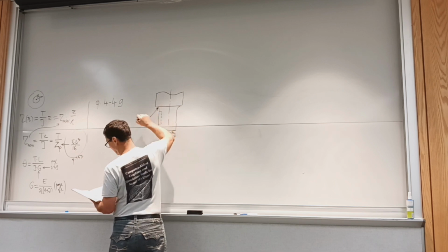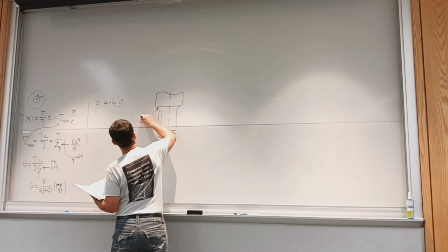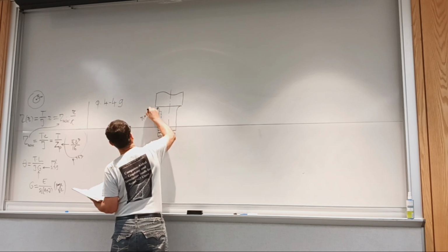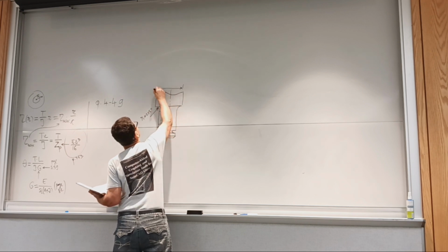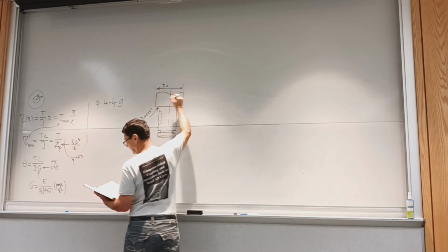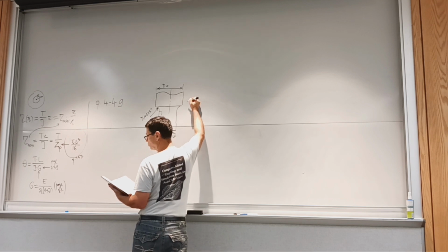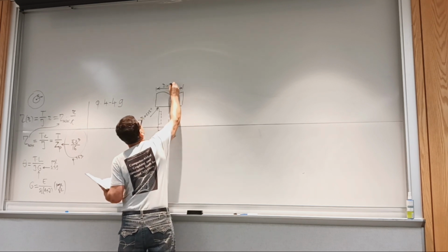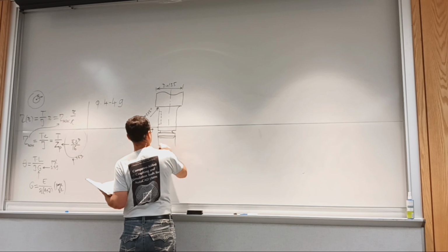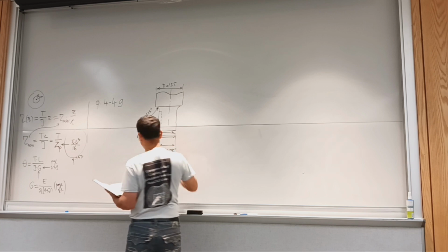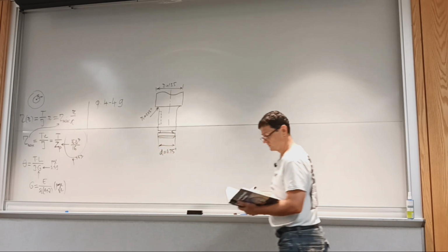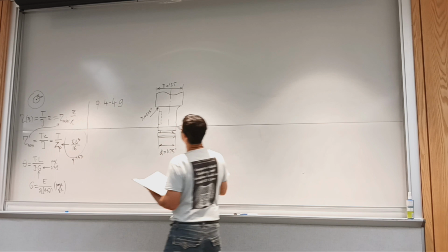Okay, we have R is the fillet radius of 0.05 inches. We have the major diameter D, and this is 1.25. And I made this 0.75, although it might be a too severe transition, but it's what I chose. So minor diameter is 0.75 inches.